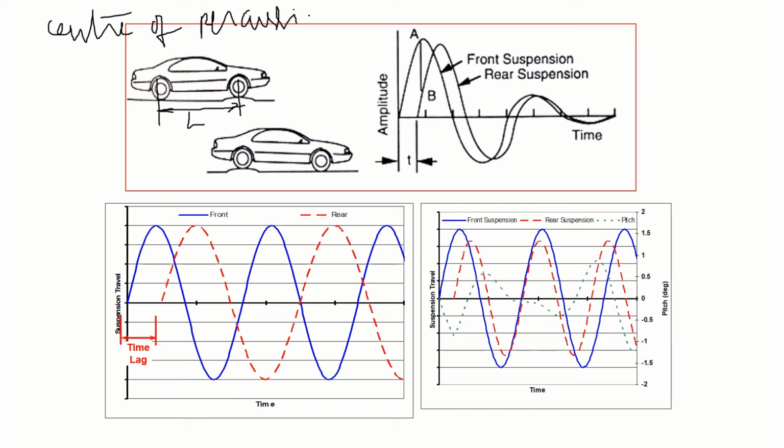What do you mean by center of percussion? If I take a cricket bat or hammer, suppose a ball hits over here and somebody is holding over here, the reaction is 0. Or if you are holding here and hit it here, the reaction is 0.